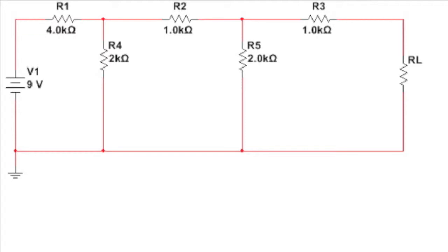Here's the circuit that I used to develop my Thevenin equivalent. Now there's a couple of important notes that I wanted to show here. First is, on the voltage source, I chose 9 volts. This is because with my DAC system, I would have two different ways to supply this voltage to my breadboard. The first would be through the 9-volt battery that is part of the breadboard, and the second is from the analog outputs from the LabView system.